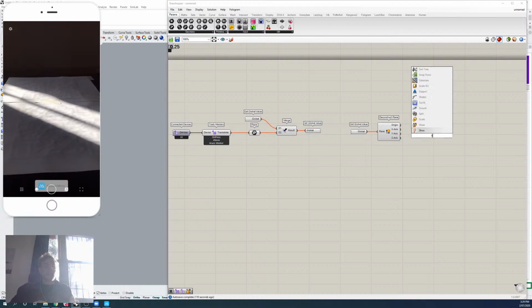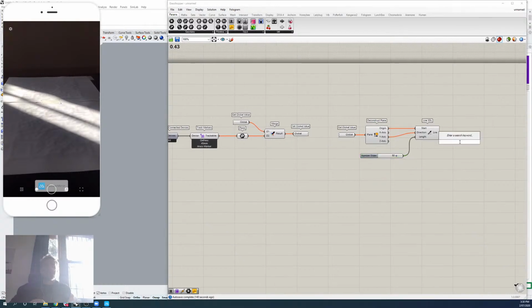Then we're going to create an SDL line. It's going to have a start point, a direction, which is going to be from the y-axis, and then a length, which depends on the width of your timber board. Let's maybe say it's a width of, I don't know, 80. So that's 80 millimeters because I'm working in millimeters. Then we're just going to loft all of those lines together, like that.